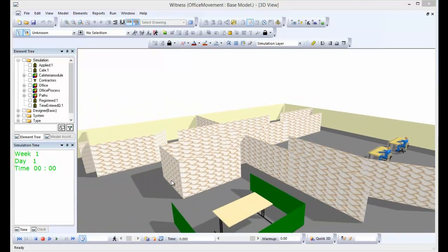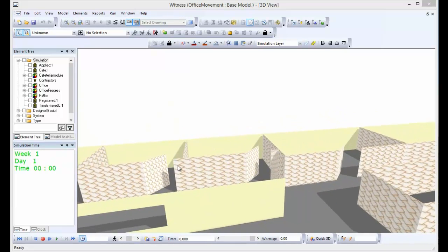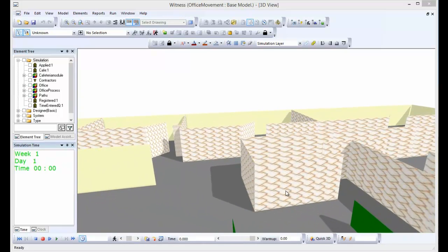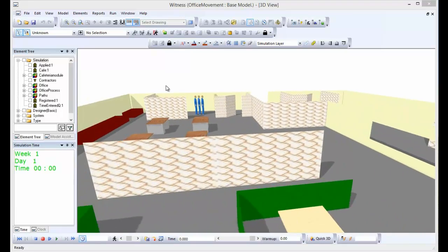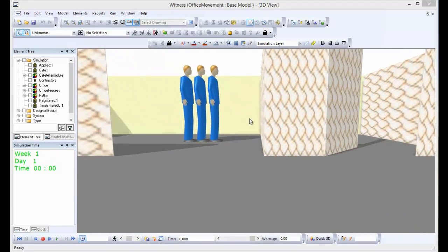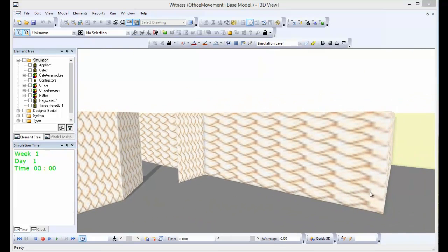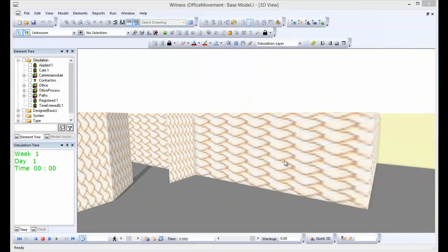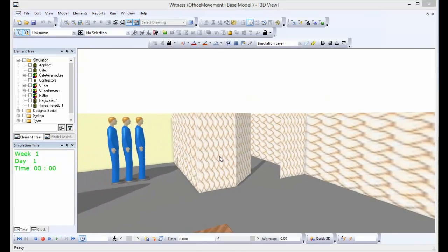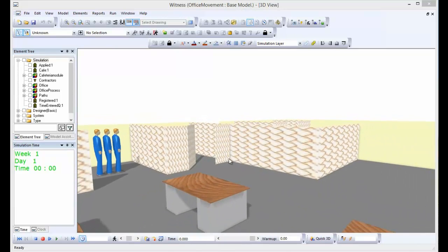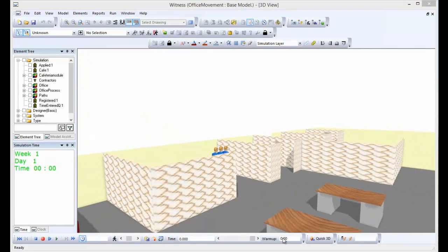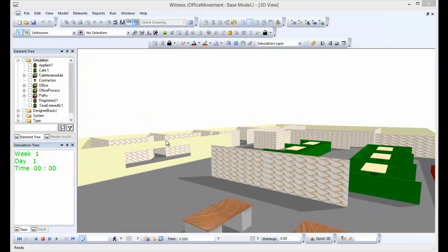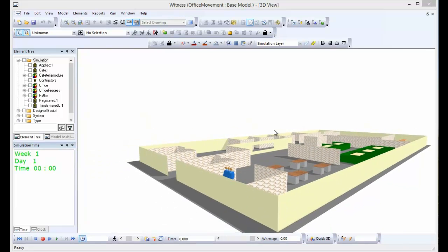When you extrude a line segment and apply a pattern to it, then the pattern will spread across the whole of that segment. Maybe it'll be clearer if I go down this end, where we can see that here we have the pattern quite well spread out on this particular wall segment. Here it's much more compacted into a smaller horizontal stretch. So if you want regular wallpaper type effects, then it's important to draw line segments of a regimented and similar width along the whole length.